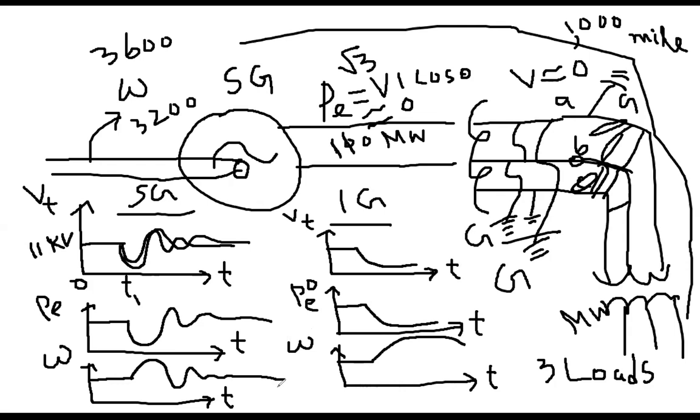Therefore, see the difference. In this case, when it was the synchronous generator, it went up and then came down, oscillating, and settled down. In this case, it went up. It looks like it is coming down, but it might not come down immediately. So therefore, see the point by point comparison. The tendency is the same. At first, the reaction is the same. Once the fault happens, it is going down. It also went down. That matches, but it did not come back.